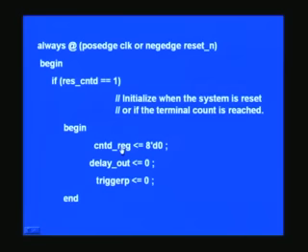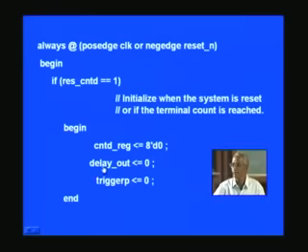So the counter, although it is a timer as such, a monoshot multivibrator, we have designed it as a counter, and this is reset here, and there is its output we have already seen as delay out, and that is also reset. And there is one more signal that we said will have the previous status of the trigger, which is also a flip flop, that also needs to be reset right at the beginning, and this being a block, we have a begin and end.